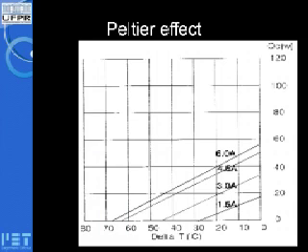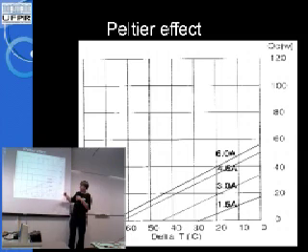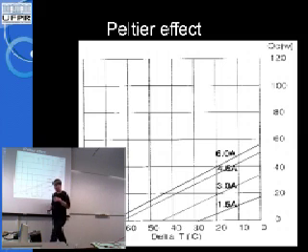As it goes to a bigger difference of temperature, this power that is pumped decreases. It reaches 0 at 65. That means the biggest difference of temperatures is 65 degrees. At this point, it can't push any more heat. It starts to let some heat pass by.